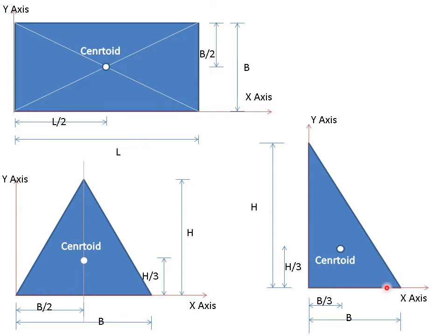So these two sides are perpendicular to each other. So this angle is 90 degree. This I call it as base denoted by B. This I call it as height H. So same equation lies here, lies at h by 3 from the base, and similarly along x-axis it will be b by 3 along x-axis measured from this vertical axis, that is y-axis.